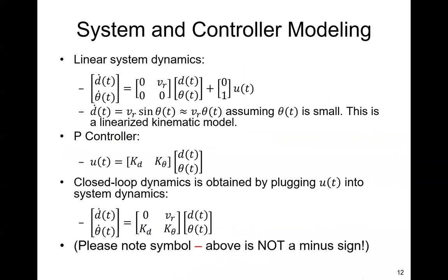And then we have the linear system dynamics by linearizing based on small angle assumption. So we have the approximation of transforming the nonlinear function sine theta to a linear function theta. So the overall system dynamic is linear. And then when we have a linear system, we can perform controller design based on well-known methods in control theory.